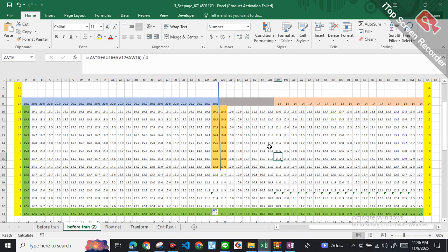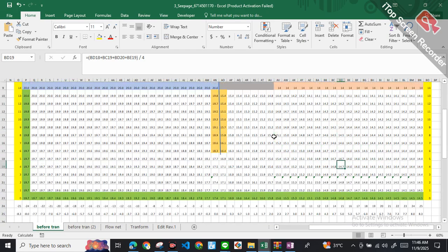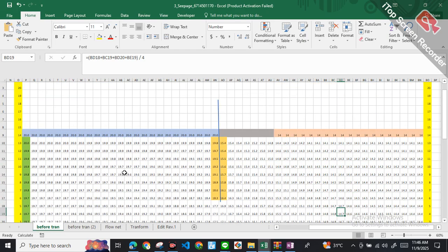So you just have to put the formula, but you need to be really careful of your boundary conditions, right? You need to be careful, like okay, I cannot go this side, or in this side also. You can choose this value a and 10 for this cell, but for this cell you have to bounce back to this value. You just do it with all the formulas and you're almost basically done with the finite analysis for your seepage.